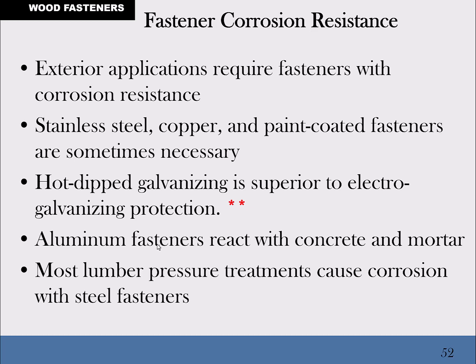And then the screw is a high carbon steel. We've got a lot of carbon in them, which they don't rust as easily either with the carbon. Hot dipped galvanized would be a superior coating to an electroplated galvanized protection. So there are some nails that you can buy that are hot dipped, and they'll have a much thicker galvanized coating compared to the other nails that you can buy that are electroplated. But the electroplated are going to be skinnier and slimmer and maybe easier to work with. So it depends on how long you need this thing you're building to last.